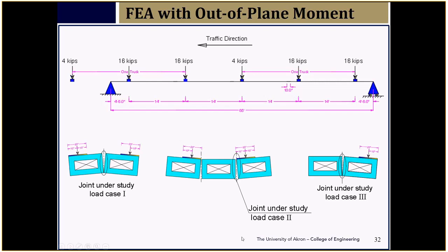And this is a new load case where we apply load to only one unit, and this is quite possible once the 2 beams are acting independent of each other. It's possible, and if the joint grout is holding them together, it's highly likely that the out of plane movement will cause tension or separation of the joint at the surface of the keyway.